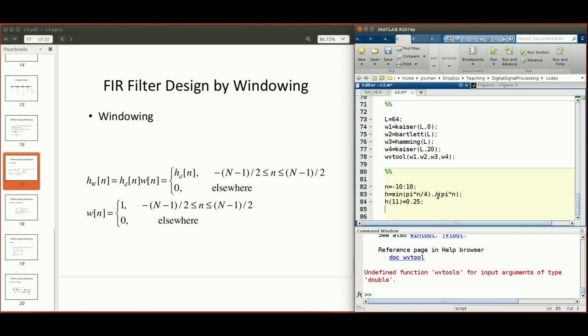So that's going to be the impulse response of our desired filter. Even though the range is fixed from -10 to 10, it's just one segment of the complete desired sinc function. The reason we're choosing this small range is because the window we're going to apply has a width controlled by this range. Everything outside of this range will be removed by the windowing anyway, so there's no reason to construct a horizontal range from -1000 to +1000. It's unnecessary, right?